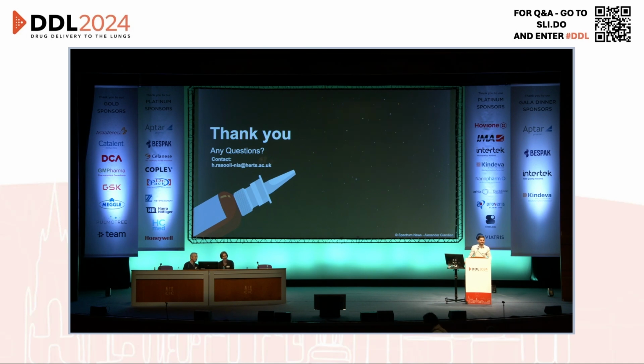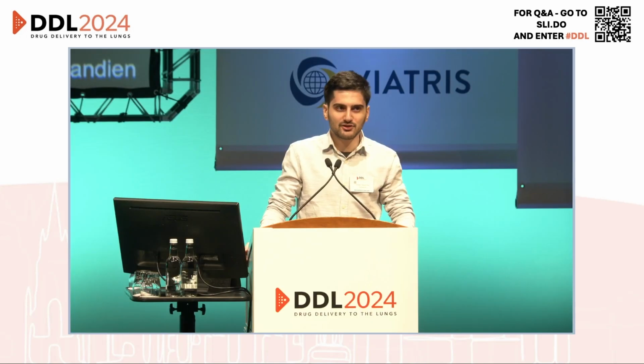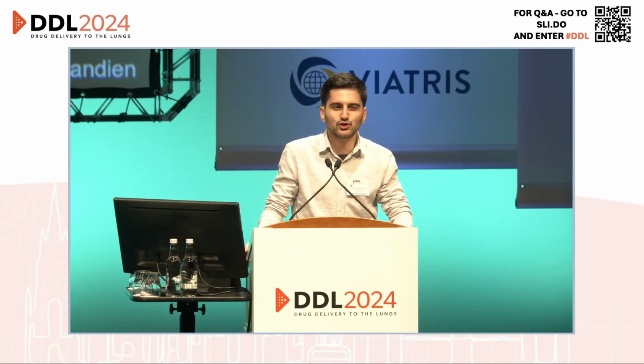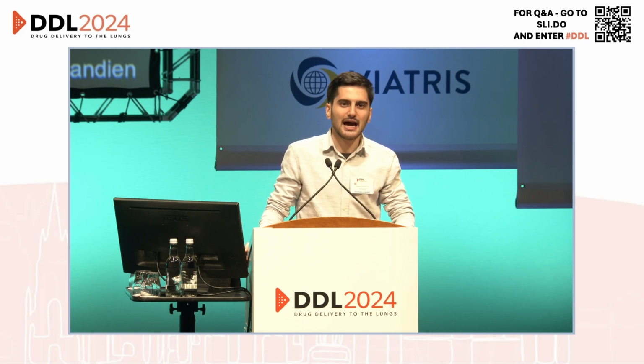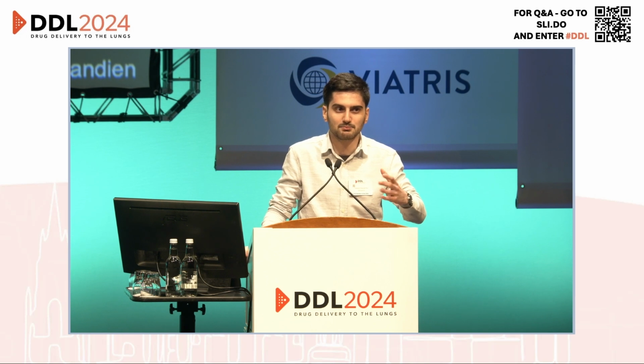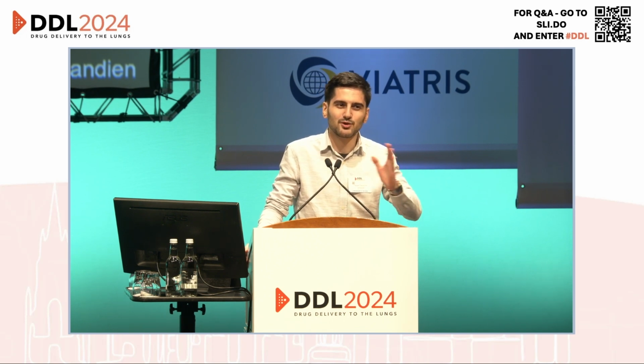Hey, I wonder if you've considered surface tension as part of the Rayleigh-Taylor instability of the droplet formulation in your model? We have considered the surface tension in these simulations. They do have a bit of an effect. However, the biggest effect of surface tension would actually be if we looked at what happens after the nozzle, because surface tension is quite important for forming the fine droplets from the liquid bulk. So it would be very important if we were looking at the atomization, but because we're only looking at the flow within the needle, it isn't as important, but we have inputted surface tension values in.